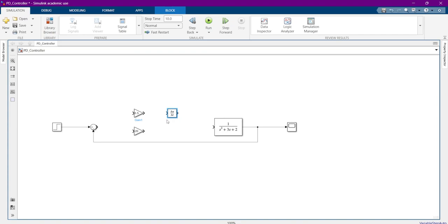Now, this is not a causal controller. I'm not going to delve into the details of the control theory about causality. But you may know that this controller configuration is not valid in real life because it's not a causal controller. In order to achieve this certain derivative action, we have to know something about the future, while we do not know anything about the future. You know that the derivative defines the slope of the error in here, but we do not know the future values of our error. So this is not causal. But we may overcome this problem of causality using other configurations. I'm not going to talk about this in this video, maybe in upcoming videos, inshallah.